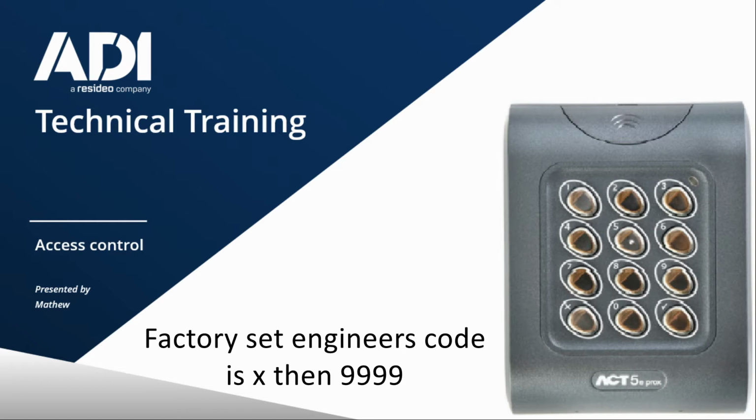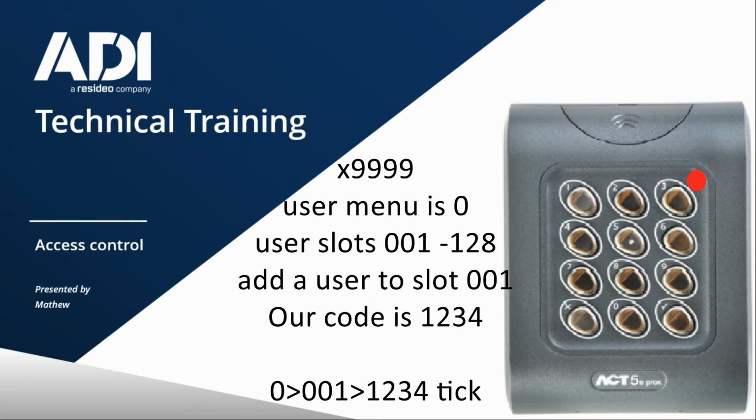So let's begin. First of all, we're logging in, so it's X and 9 4 times. You can hear that reassurance tone. We're logged in. So first of all, I'm going to add a user, which is pressing 0. The LED light flashes red. I'm going to edit user 1. So remember, user 1 will be 001.